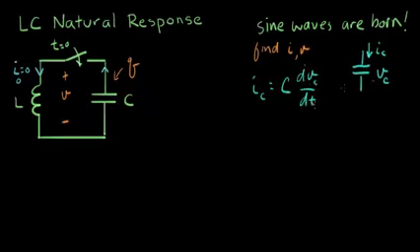Now if we look here, VC is the same as V here. Positive sign at the top, negative sign at the bottom. So VC and V are the same. But for I, we have to be careful. I is in the opposite direction of the current that I picked for our independent variable. So that's upside down. There's a negative sign we get to flip here, so I equals negative C dV/dt. So that's the IV equation for our particular circuit. We have that little extra negative sign.